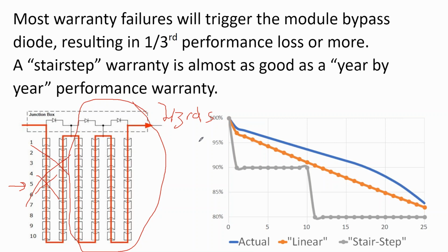But whenever there's a very precise drop, like all of my panels are producing this much power, but this one panel is producing exactly 3/4 less or exactly 2/3 less, it's a bypass diode issue. There's a cell that's gone wrong, and I've had no problem using regular solar distributors where, if an issue like this is caught within the first year of the project, getting that module replaced under the manufacturer warranty.